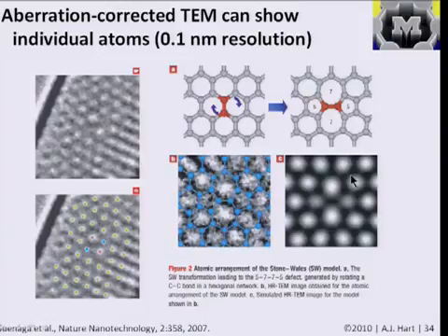And so these images just show, here they're taking a high-resolution picture of an individual carbon nanotube and trying to pinpoint the placement of the individual atoms in the hexagonal lattice. And this doesn't look exactly like a hexagonal lattice because of the way the tube is maintained, but basically what they've done here is they've mapped out what they show is a defect in the structure, and here they showed the existence of this so-called Stone-Wales defect, where you have, instead of 4 hexagons, 2 pentagons and 2 heptagons, and we'll see another flavor of that when we start talking about mechanical properties next week.